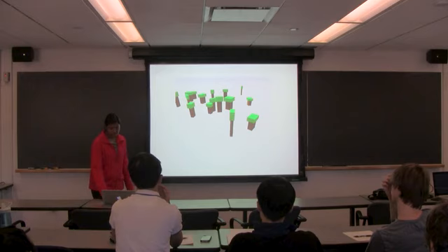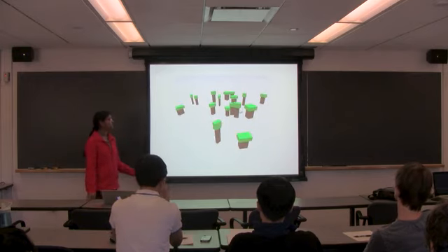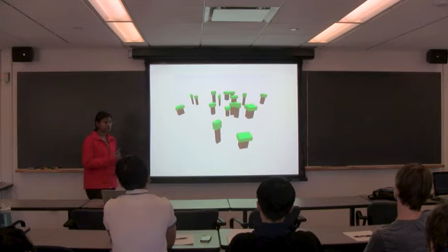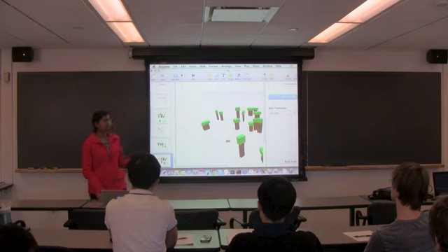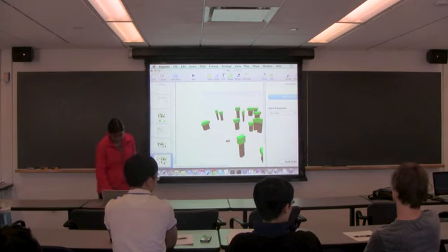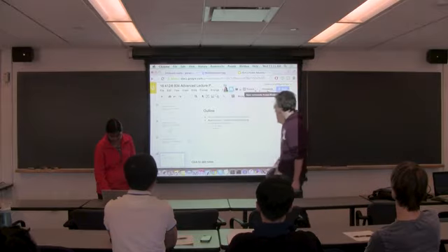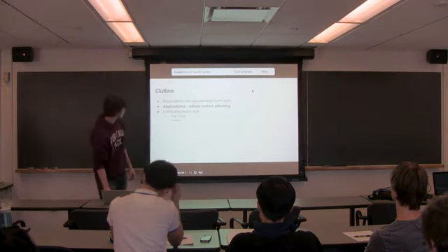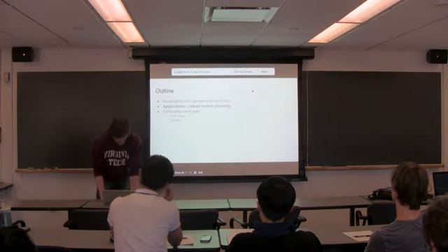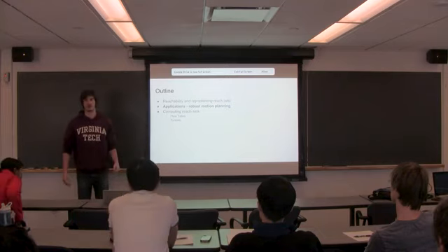So we have seen how to use funnels to do robust motion planning. We have seen how to do offline planning and how to do online planning using a sequence of funnels and funnel libraries. Now we'll talk more about computing these funnels and flow tubes with other kinds of presets. So I'm going to talk about how to actually compute them, how to compute flow tubes and funnels generally.